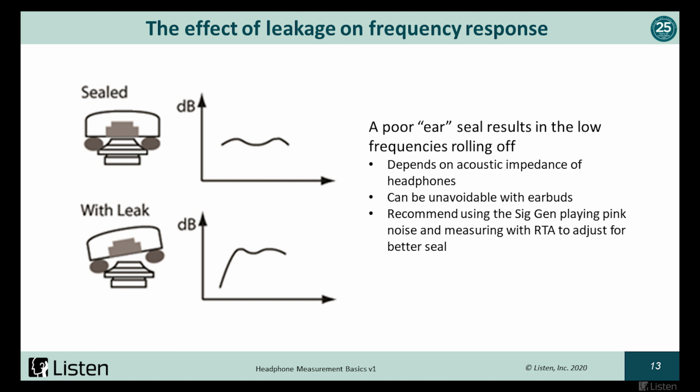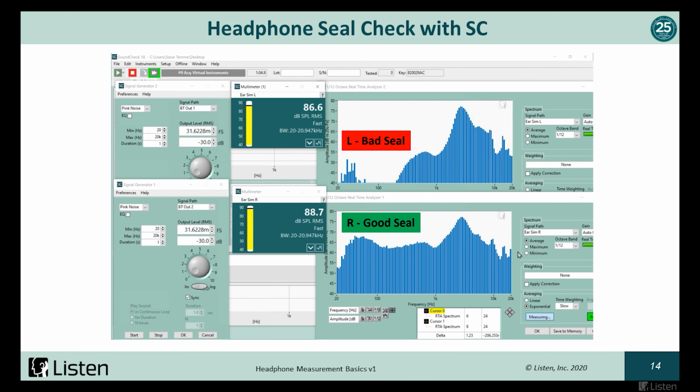So what I recommend whenever we want to measure our headphones is that we mount the headphone on the ear simulator and try to play around a little bit with the seal. If we use a signal generator playing pink noise and bring up a real-time analyzer, we can see in real time if we have a good seal or not. I'm not going to demonstrate this live, but I think you'll get the point.